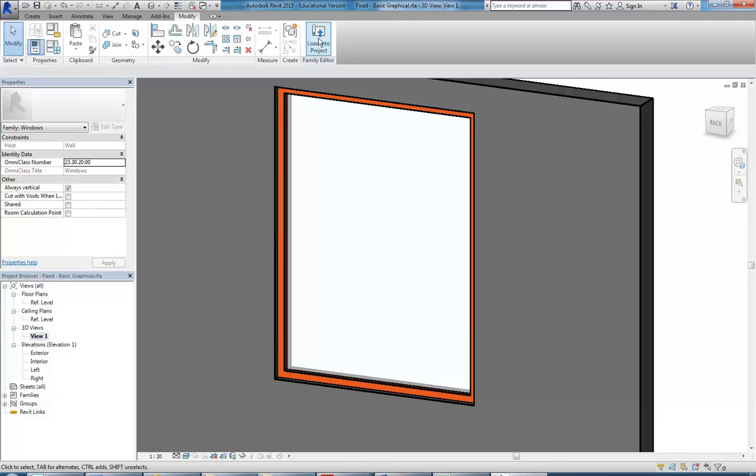So that one now, I'll just finish off with that second transom. Notice I left that transom thickness from the one below. I can use the same parameter to adjust both of those things. So if I go into family types now, and my floor might be a different thickness, if I change that transom thickness there to say 200, then they both change. So maybe 150 is what I've got the floor at now, so I'll leave it at that.